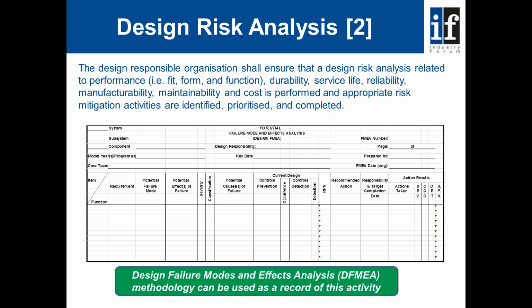And when we consider things like key characteristics, then part of the design FMEA process would be to start anticipating which features of the design are either going to be safety critical, reliability critical, or going to give problems with achieving regulatory compliance.